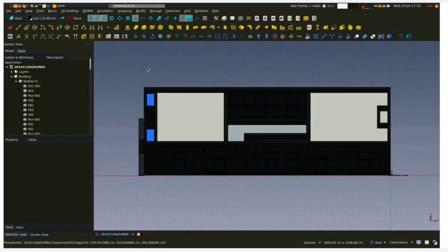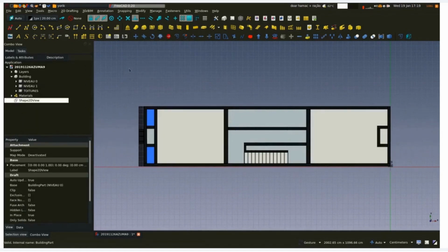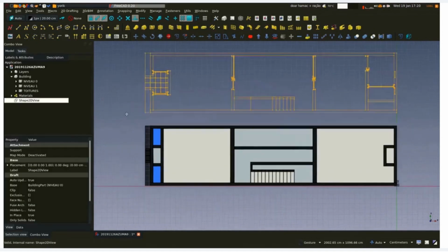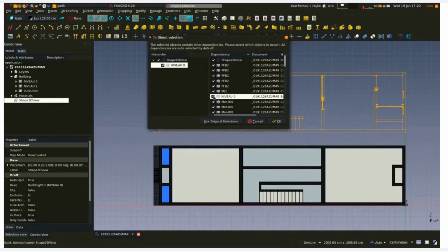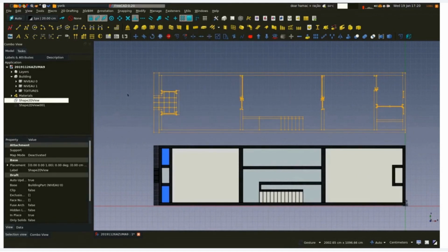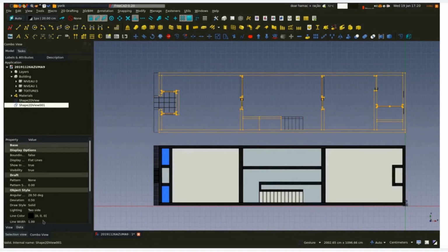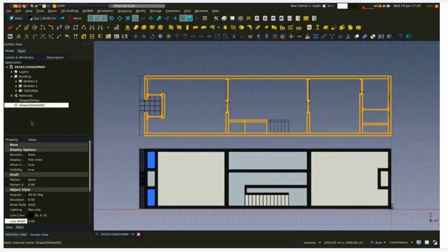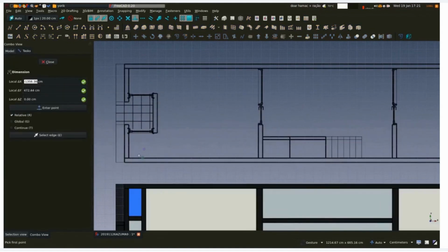Another very quick, interesting thing to do with the model that you import in FreeCAD is just to extract a quick plan view, for example. So we use this Shape2D tool to just extract a plan view from a level. We make a copy of it, and we change its setting to just show the cut lines, and by changing the thickness of this cut line, we now have a perfect plan with cut geometry and viewed geometry, project geometry. So we have a nice plan view.